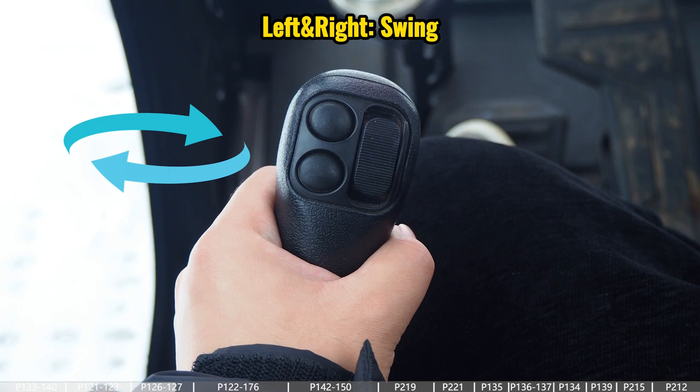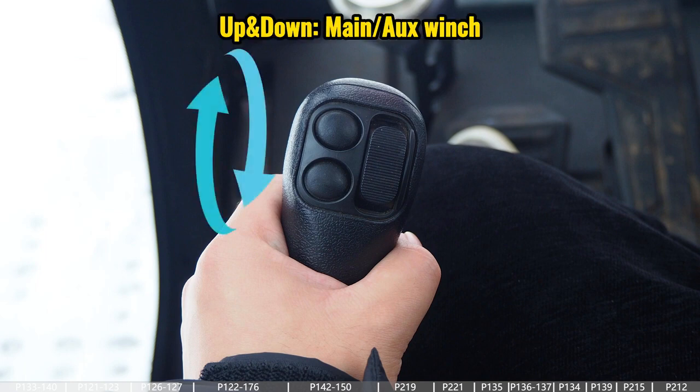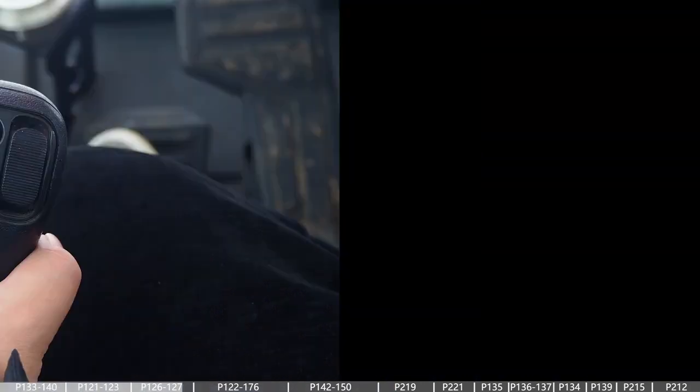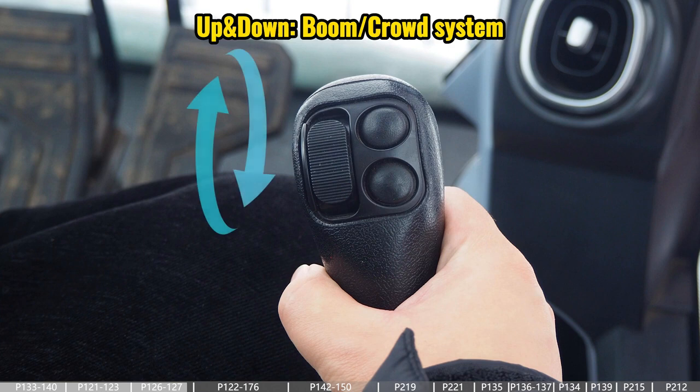Turning left or right for the left joystick is the swing of the undercarriage, and up and down for the left joystick is a switch between the main winch or auxiliary winch up and down. And for the right joystick, left and right is for the rotation of the rotary, and up and down is for the up and down of the crowd system or the boom.